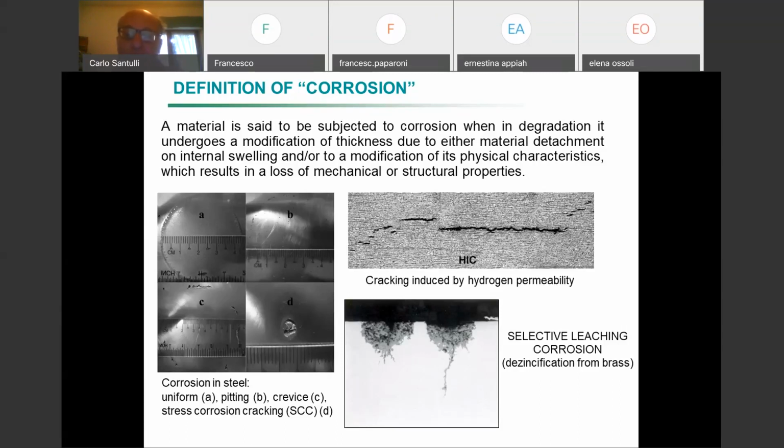Because, for example, water vapor also can penetrate the material. Or even hydrogen may penetrate. In some situations, you may have a kind of hydrogen embrittlement. You work with acids, for example. In acids, you have hydrogen. Then hydrogen can penetrate the material as a result.